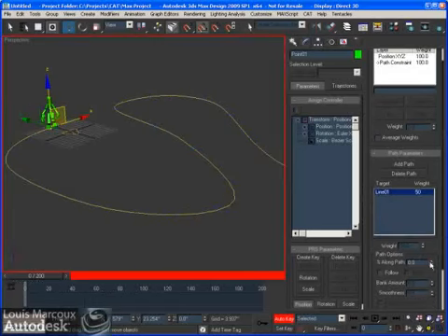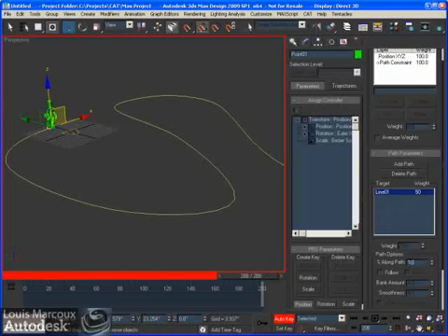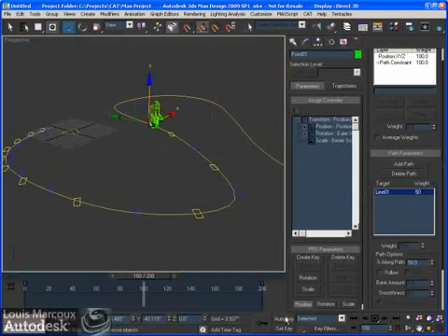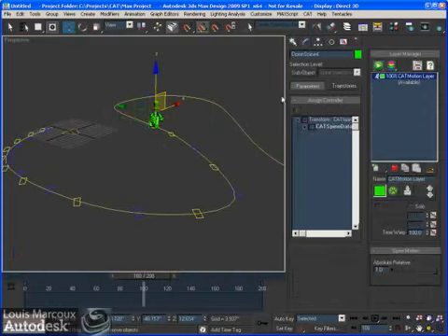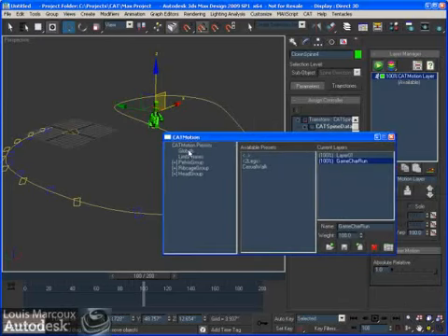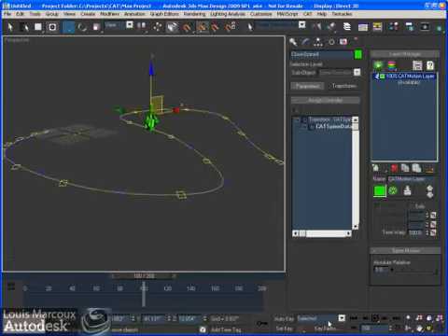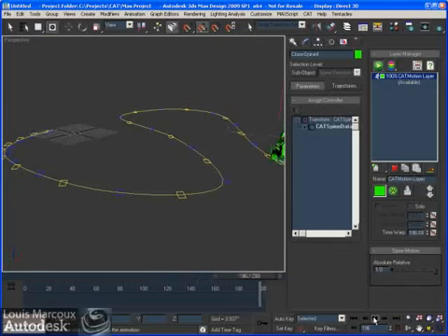And have it go from 0% at the beginning to 100% at the end. So now here you see that it stops at 100, and that's something I want to mention: if I go to the CAT motion panel, global presets here, I see that the CAT motion range goes from 0 to 100. If I want to create a 200 frame animation, I'm going to say 200, and now what we're going to get is the motion of the character for the full animation. So it's going to start, and then it's going to start running and try to stay with those footsteps that are kind of like this.